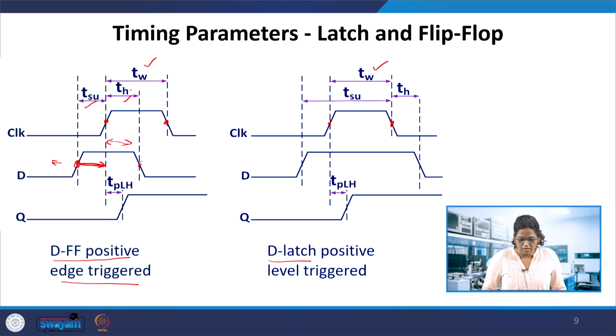So if we consider the setup time and hold time of the latch, the data is changing over here, but the clock will be active till this point. So the setup time is this duration for the latch. It is different from the flip flop case, where it is up to the clock edge, whereas here it goes up to the negative edge, where the clock becomes inactive. And hold time is after it becomes inactive, where the data changes. So the allowed change is the hold time. The data should be stable, not changing, that is TH, during which data should not be changing.